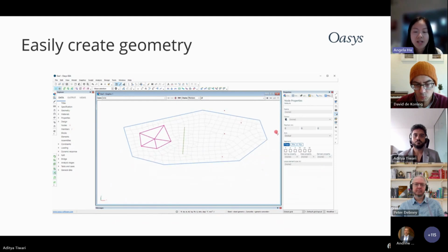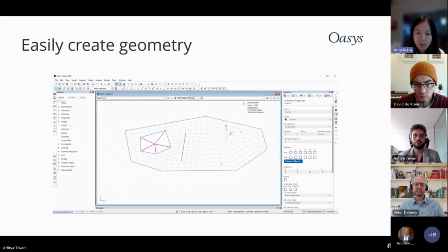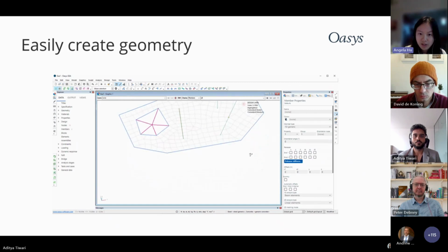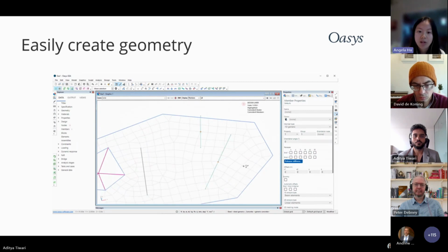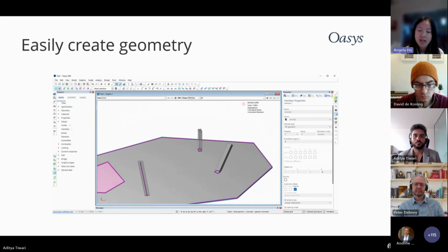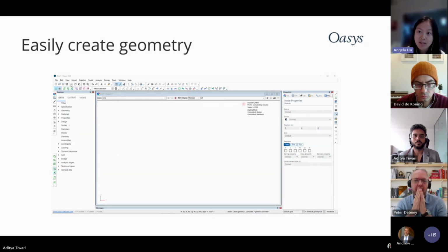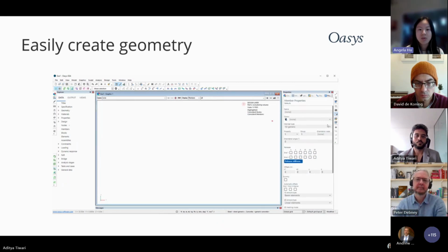Another thing that you could do is add columns or braces that intersect with that slab. And once again, when you do that, you can see that all of the intersection points node out. And one more final thing I want to show you is that you can create something called internal offsets, which creates a void the size of the column section, and it ties rigid constraints to it automatically so that you're not getting these peak stresses.